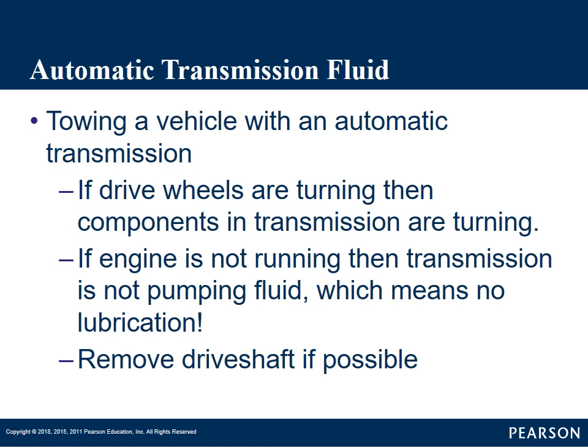If we are towing a vehicle with an automatic transmission a short distance, a few miles, and as long as you don't go too fast, definitely not over 25 or 30, you'll probably be perfectly fine. If your drive wheels are turning, you probably won't do much damage.